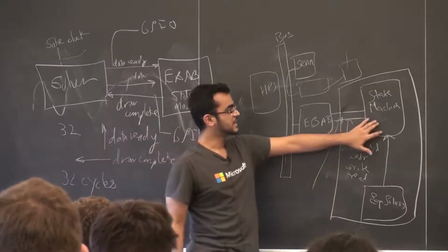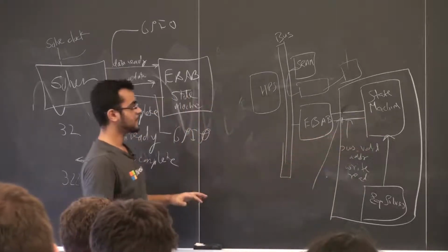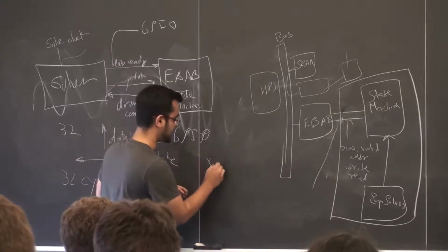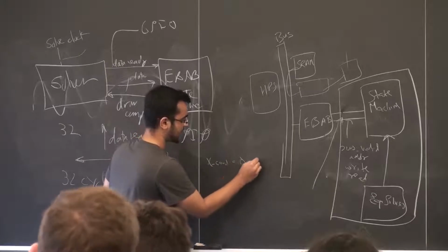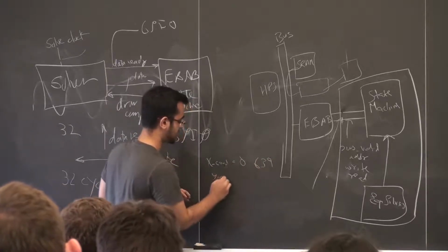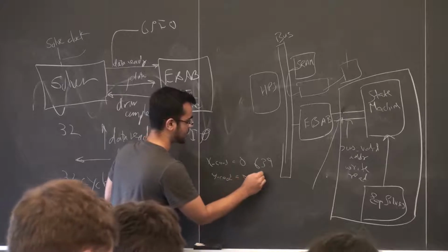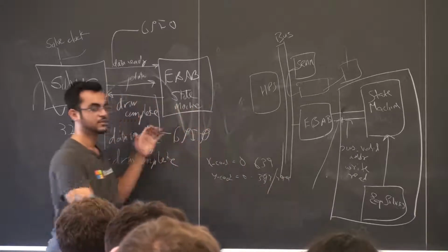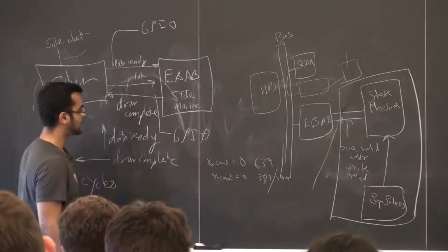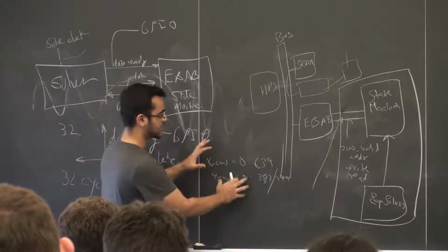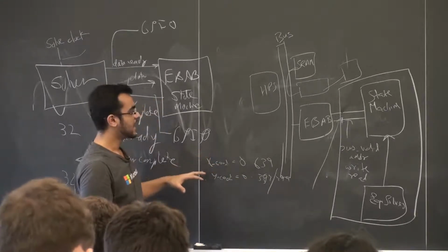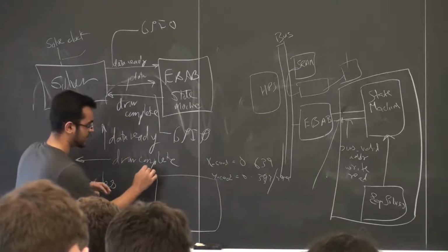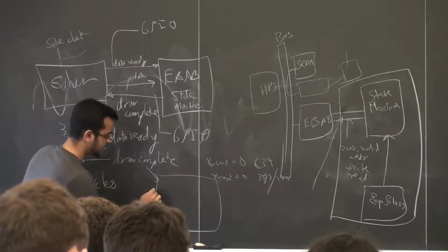What I should see is that my state machine writes 0 to all pixels, for x coordinate starting from 0 to 639, and y coordinate starting from 0 to whatever, 399 or 479. So it should clear out the entire screen. That should be what my initial state does, and after some point of time, if this is my screen, I should set the x coordinate to 0, and then I should plot.